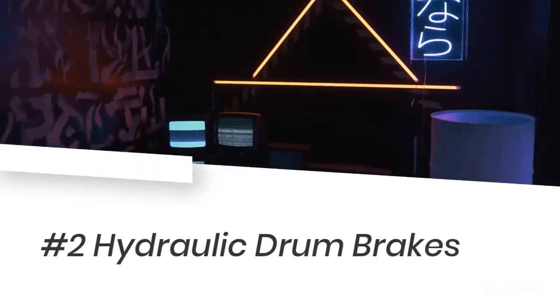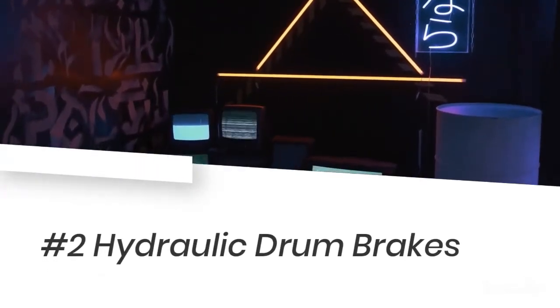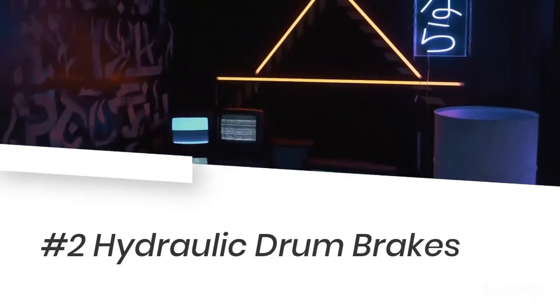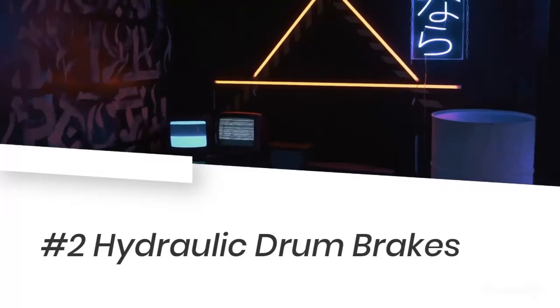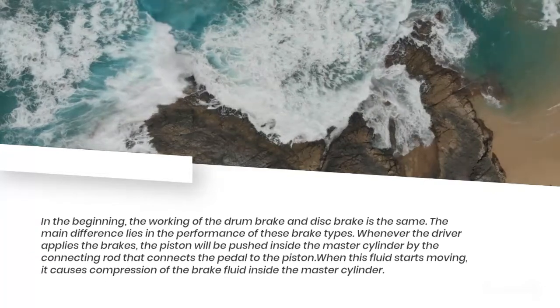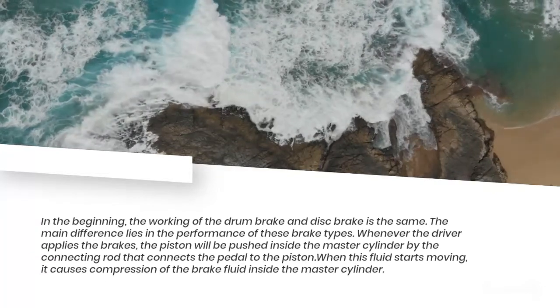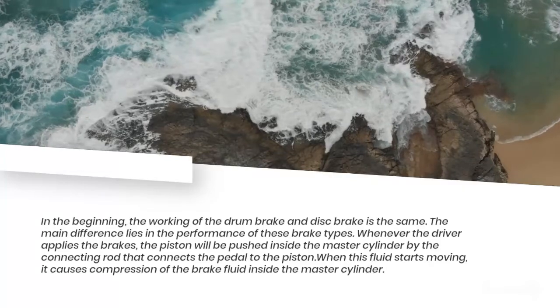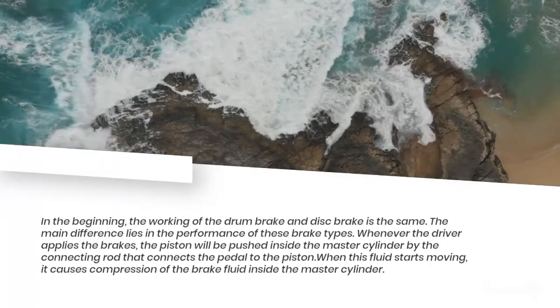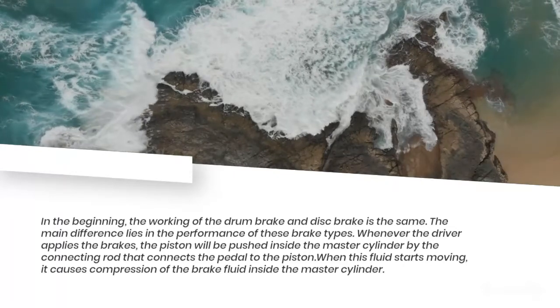Number 2. Hydraulic drum brakes. In the beginning, the working of the drum brake and disc brake is the same. The main difference lies in the performance of these brake types. Whenever the driver applies the brakes, the piston will be pushed inside the master cylinder by the connecting rod that connects the pedal to the piston.